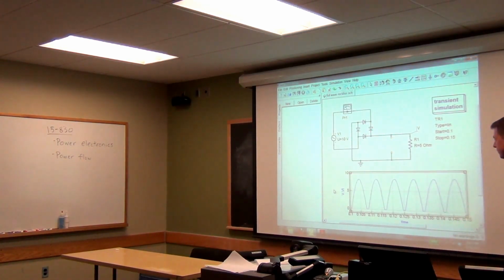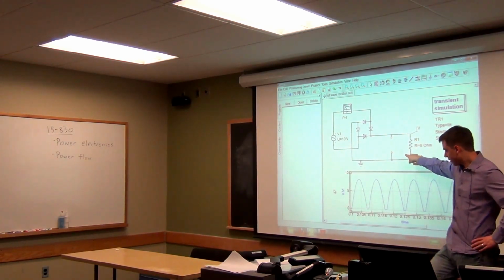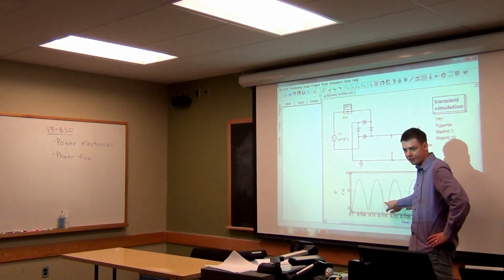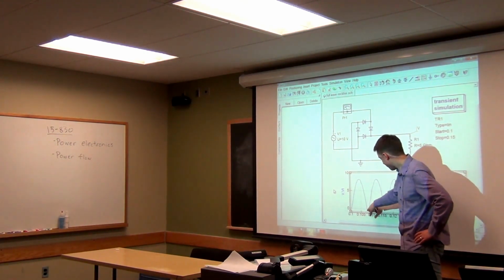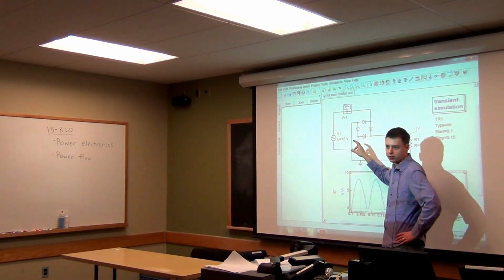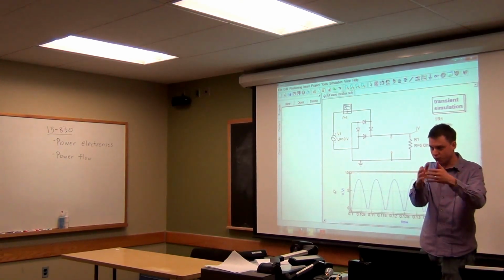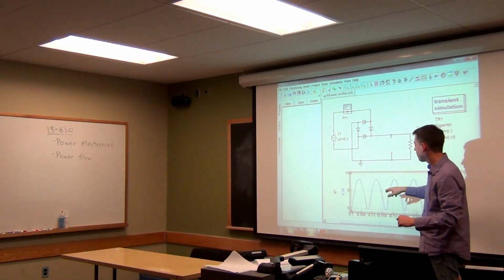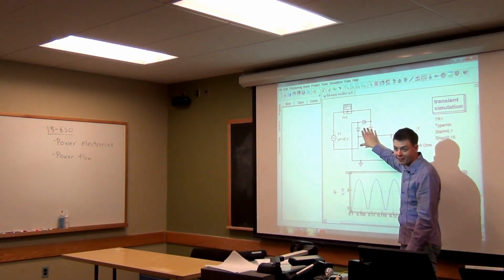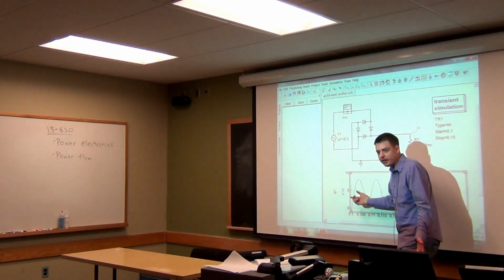All right. So what's happened here is that the voltage that it sees here, we get it for every single phase. This little notch here, don't worry, it's actually just due to the fact that it's modeling that these are not ideal diodes. They take a little bit of time before they can switch and allow some current to flow through, but after it's kind of built up on the other side. So it's actually modeling the fact that they're not ideal diodes, this package. So what we see is what we expect, right?